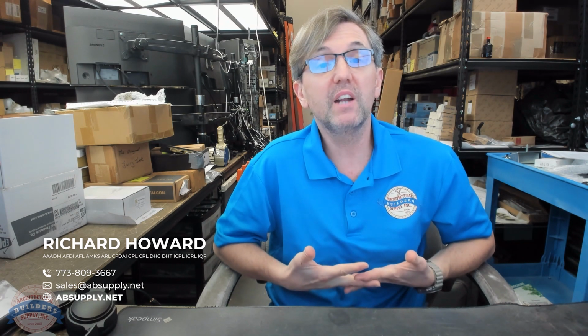But I thought to myself, the world's largest retailer, who knows how many billions of dollars in gross sales a year, and their spec calls for a 20-gauge honeycomb door. You can't get any less expensive than that and still call it a hollow metal door. So that's honeycomb. The upside is it's inexpensive and it is durable.